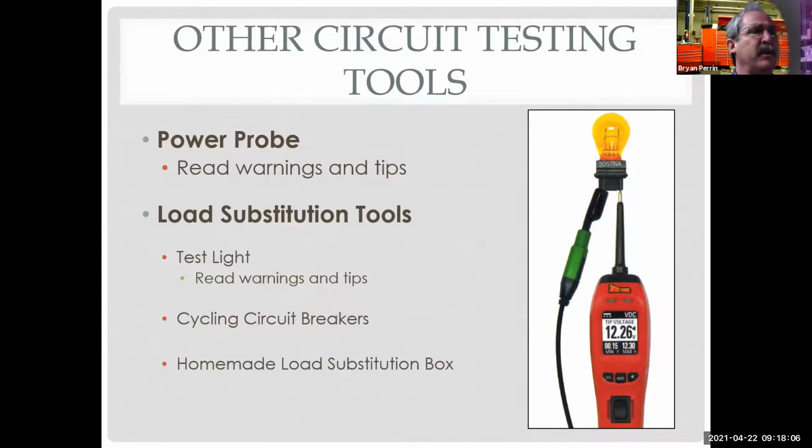But believe it or not, I really don't use it for the voltmeter as much as I use it for the fact it has a red and a green LED in it, and it beeps a different sound whether it's on power or ground. And that beeping tells me that I don't just have voltage potential, but I actually have voltage I can do something with. So very quickly I can see, hey, I got 12 volts, but it's just voltage potential. I can't do anything with it. Or hey, I got 12 volts that's beeping at me and telling me it's ready to power up a light bulb. Or ground. Hey, I got a good ground here.